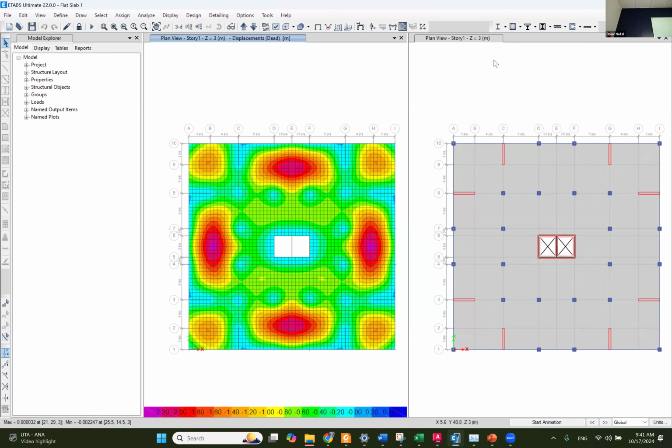We're going to get in depth, well, not in depth, but I'm going to give you a summary of what we do in the dynamic analysis. So right now you understand that if I want to get the bending moment of the slab, I need the mesh to be accurate. But if I want to do lateral load analysis, maybe the mesh can be bigger so that I can model the mass, not the bending moment. I'm just giving you some hints why we do this.